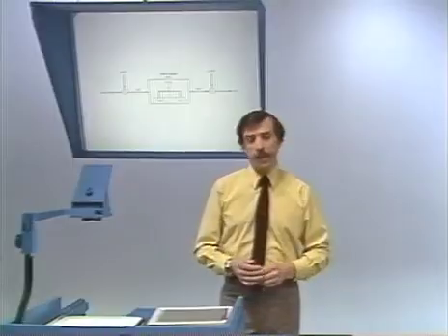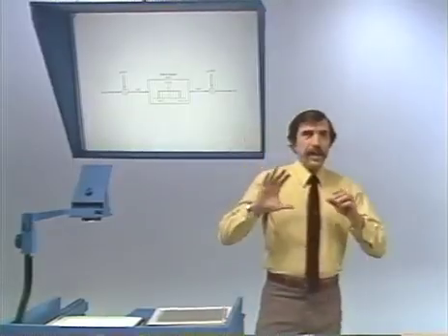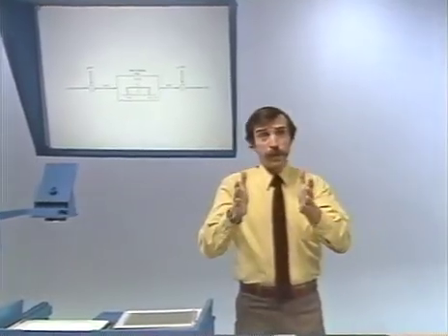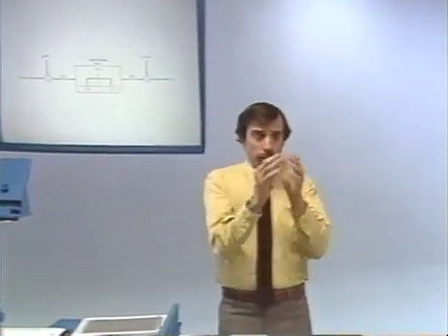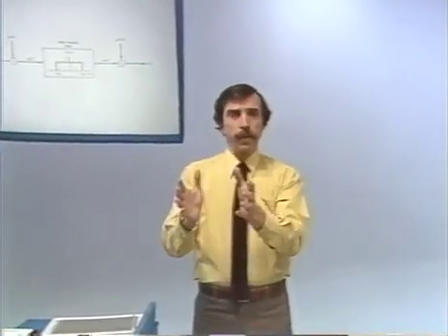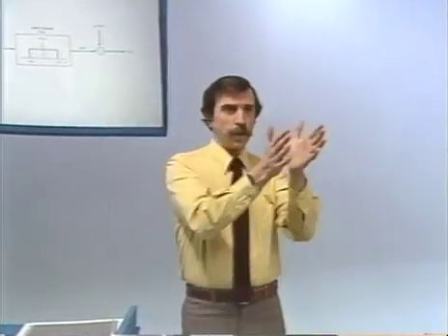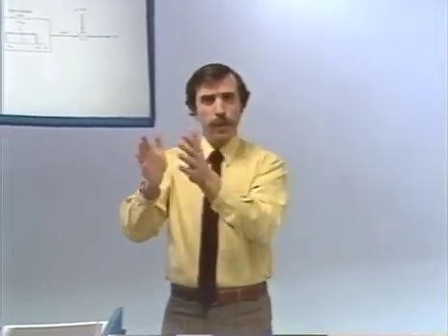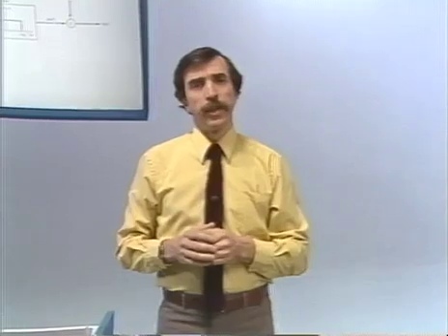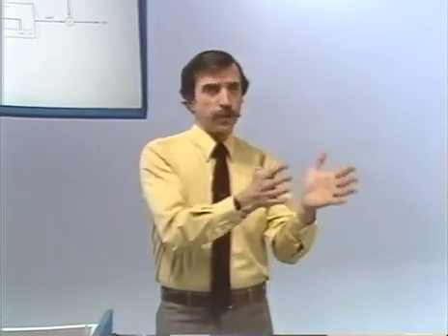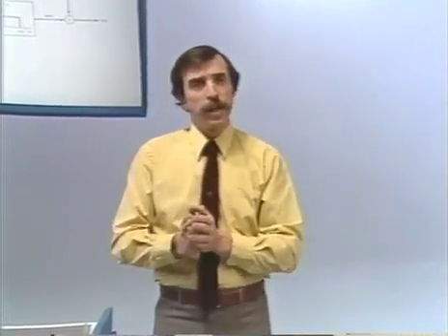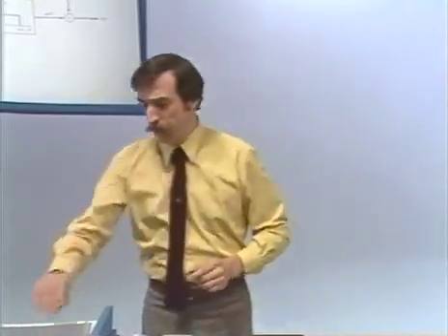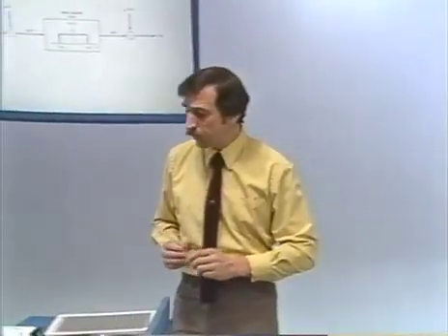And kind of here's the idea. If we have a signal and we want to think of a filter which we want to move along the signal, one way to do it is to somehow have filters that move along the signal. The other possibility is to keep the filter fixed and let the signal move in frequency in front of the filter.